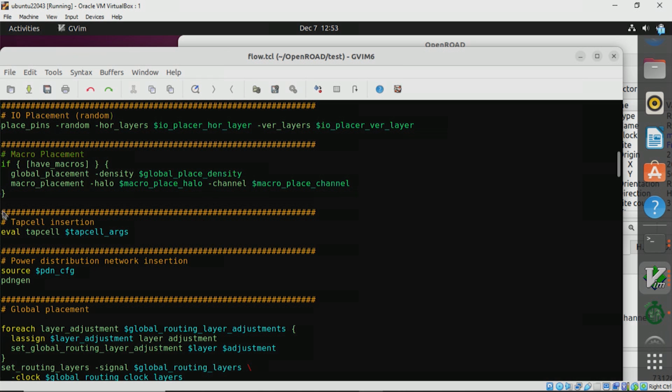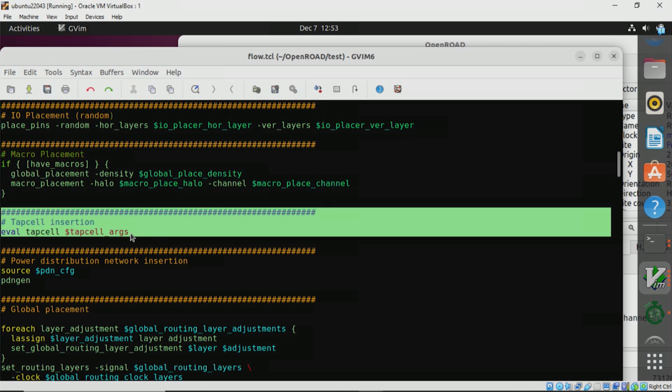Okay. So, this tap cell is essential in your design. If you do not place it, the tool will not tell you that there is an error in your design until you specifically write a report on the tap cell checks. However, the chip will never work.